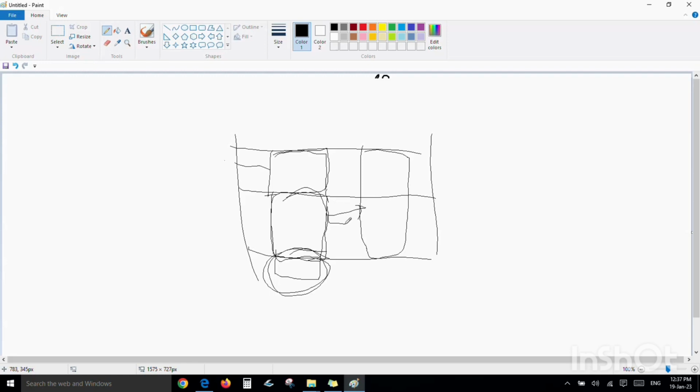And this should always be placed near to IO pins. Why is that? It is easy for macro port to macro communication. If there are a large number of signals and it is far away from the IO pin, definitely the signal is going to be degraded. That shouldn't be degraded, so that is what we need to do.